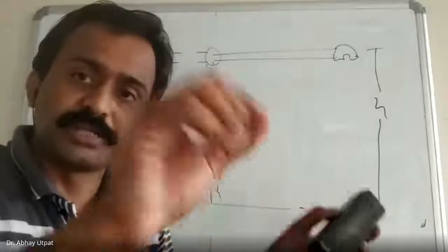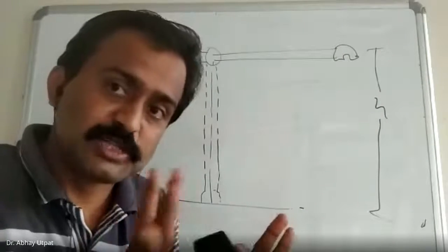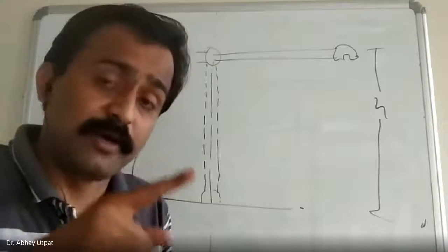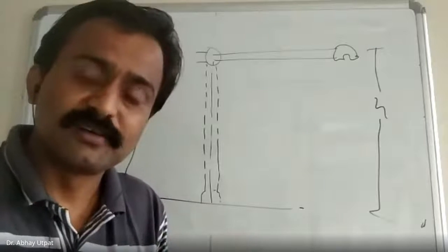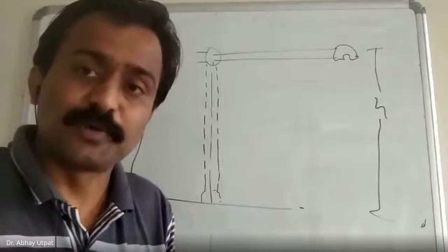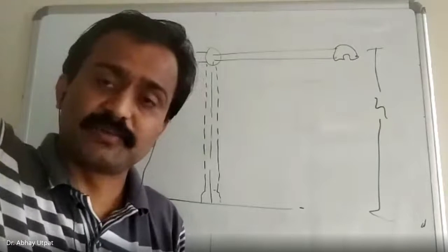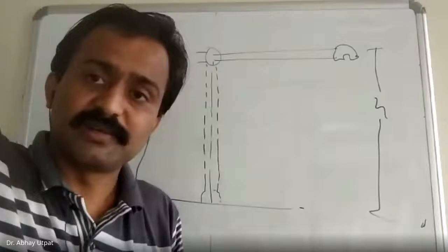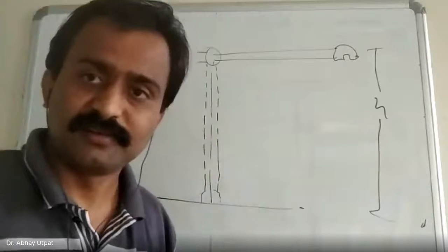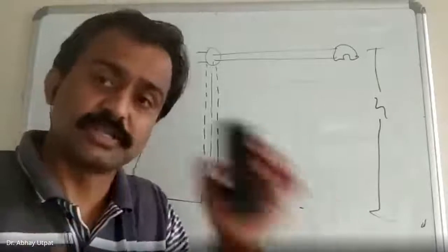Now, this is your prediction as a design engineer. Now, the same specimen you will use in the component. But whether that is so plain, no. It may have a keyhole, it may have oil marks, it may have grooves. So in such a case, your stress concentration increases and the component may fail below 200. So situations like keyholes, oil holes, grooves, stamp marks are represented by the notch here. So the susceptibility of a material to failure in the presence of a notch is called notch sensitivity.